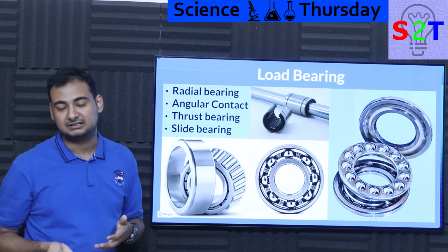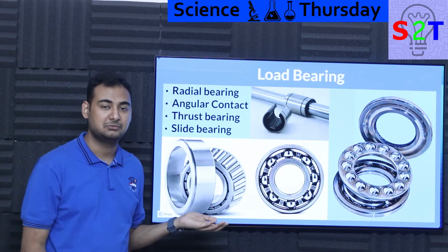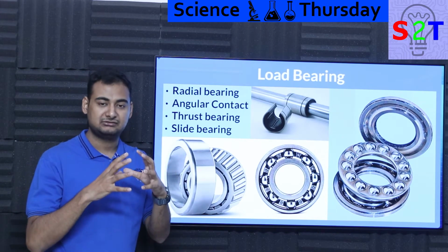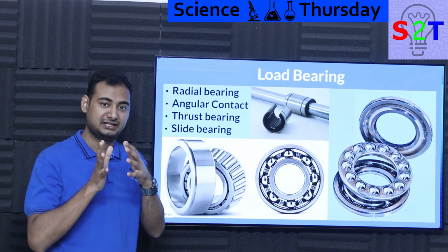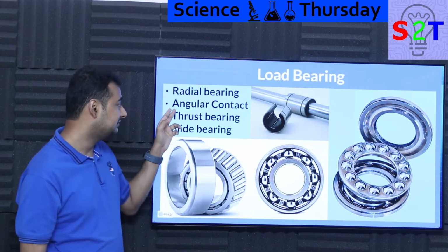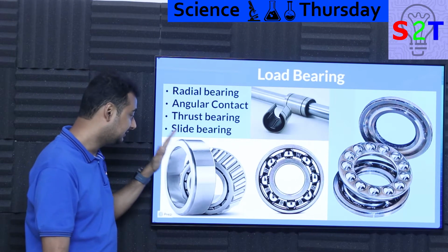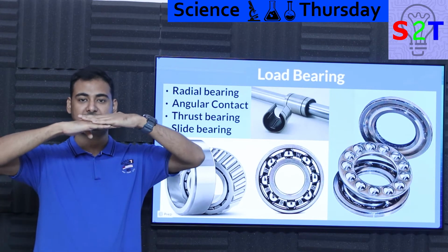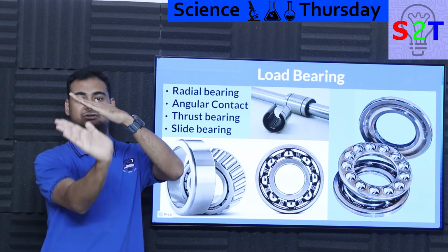And again, ball bearings are rated for equipment, so you can find a ball bearing that is well suited for your load. But if you have a scenario where, rather than rotational load, it could go either way, you will not want to use that. In those scenarios, you want to use angular contact bearings. Now these bearings are basically roller bearings, but instead of perpendicular, they have a cone to them. Basically, this is how the cone is.